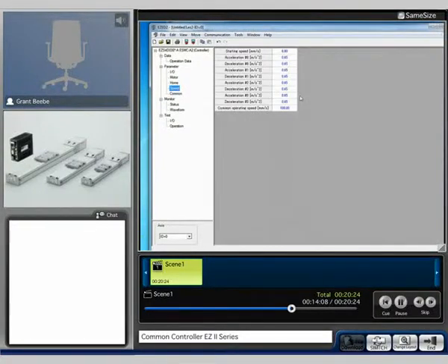Under the speed parameter, we can set a common starting speed, and then we have, again, 4 different acceleration profiles to choose from, each with its own accel and decel setting. And then we can also set a common operating speed. Now, the common starting and operating speed are going to be beneficial for when jogging the unit into place.